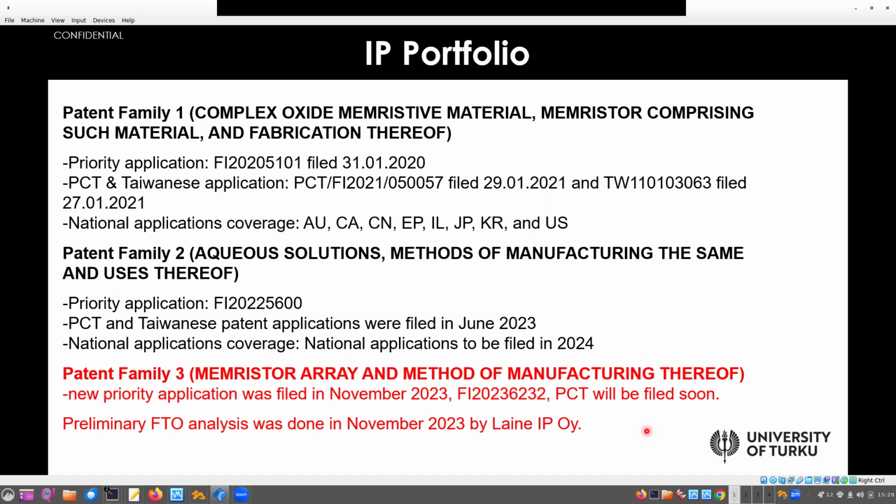crossbar network. Maybe a few words, Paturi, now regarding the competitors. I guess you can do it with 3 layers, and the existing stuff is up to 70 layers, isn't it? Yeah, it depends on who's doing it. Yeah, but generally right. There's really a lot of layers, because all this hafnium oxide, titanium oxide, these are really good insulators. So you need to have a lot of metallic layers as the bottom electrode, but we can use the same material as the bottom electrode.